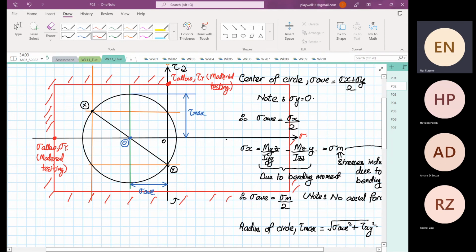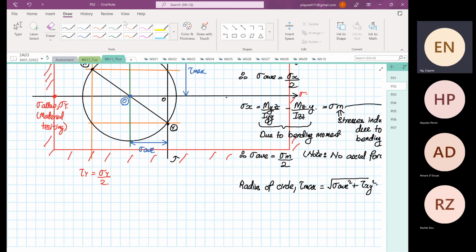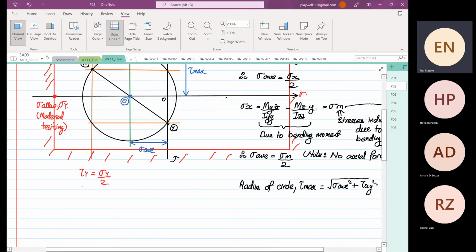So we realize that the shear yield is half of the normal stress yield. That's why you count my boxes: on the vertical there are 6 boxes on the horizontal, I have to draw 12 for that reason. So due to this relationship, we know that the normal stress yield is equal to twice the shear yield. So this value down here is the smaller value.